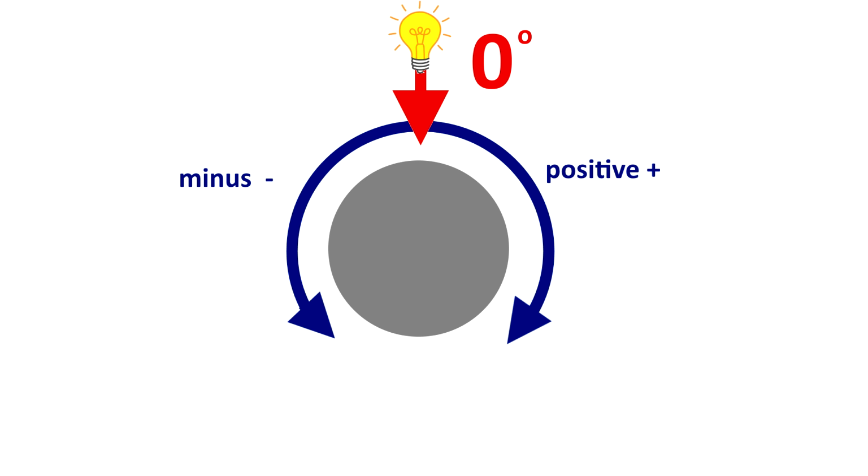So from that straight down being the 0 degree reference, counterclockwise is negative degrees, and the positive direction is to the clockwise direction. Remember this system of measurement because it's the same one used in arcs and start and stop points for some of the objects we're going to look at later.